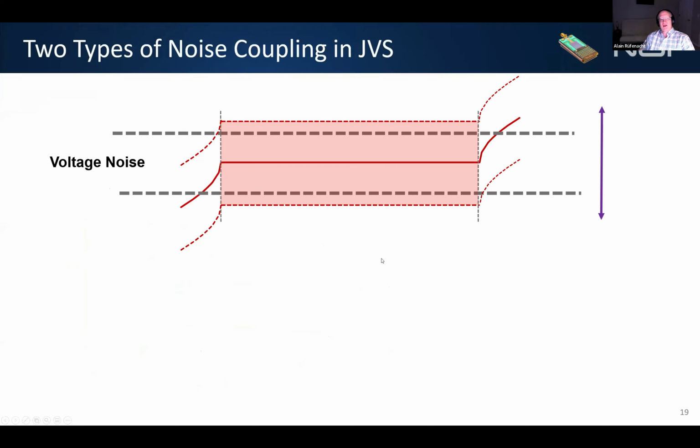Briefly, before going to the applications, I would like to mention two types of noise we see in Josephson junctions. So here's like a traditional IV curve. And what noise can we obtain? We can have voltage noise. A voltage noise can happen, for instance, if you use RF synthesizer with a lot of phase noise. So in average, the frequency is right, but the frequency basically fluctuates a little bit around the average value. So that will generate a voltage swing here. So typically that's not the end of a deal, because if you have some noise, you can average it, assuming you do an Allan variance and you know what range you can operate and do the averaging.